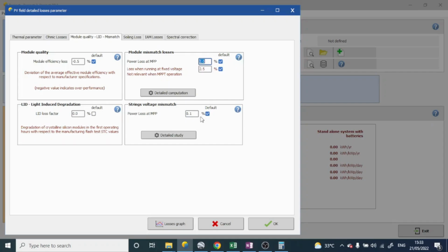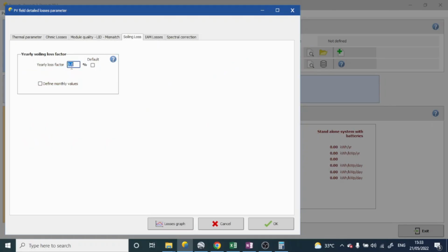That is why we try to keep it at 0.0, but for understanding we can take it as 0.1%. And if you have a higher shading parameter or frequent shading on one of the solar panels, we can change it up to 0.5 also in that particular case. So here we'll keep it at 0.1 as the software has suggested.